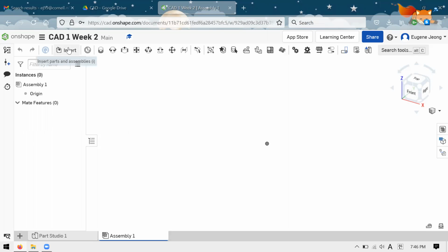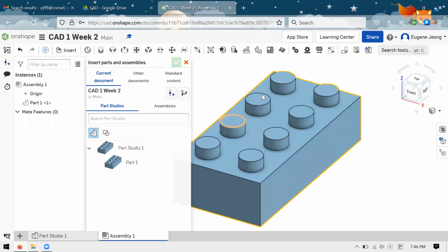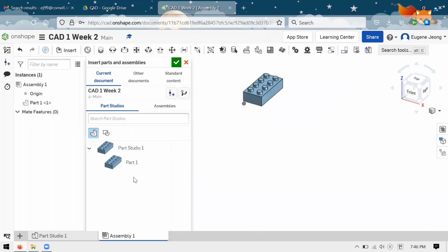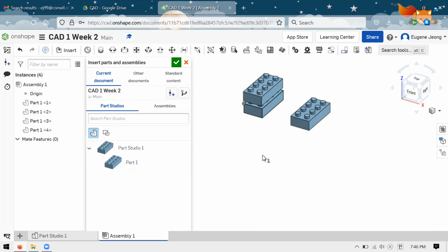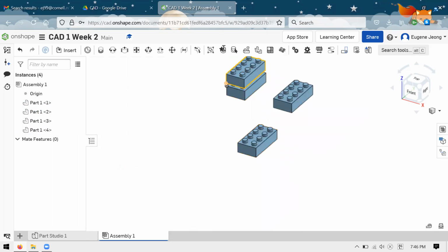Okay, great. So now that we're here, we hit insert. We select part 1 within Part Studio 1, which is this. And we can just click, click, click, as many as you want. Click the green check mark. And now we're here. So if you have any questions up to here, please ask.